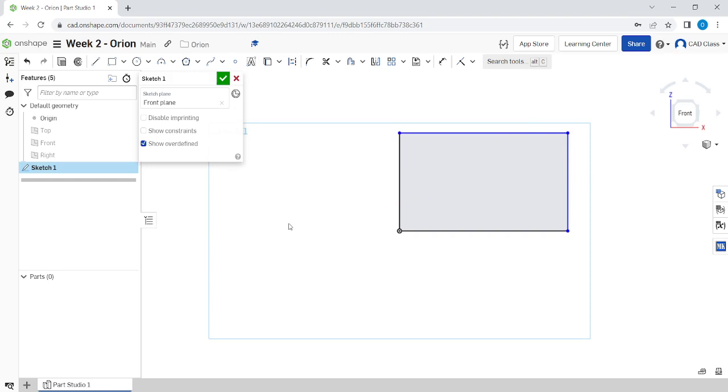And having non-fully constrained geometry is very bad for a parametric model, because you'll build this complicated model, and you'll change something, and because of the model's parametric nature, it will recalculate all the geometry. Then if you have unconstrained geometry, you don't know what the solver will do with that geometry, and it basically will do something that a lot of CAD people call exploding, right?